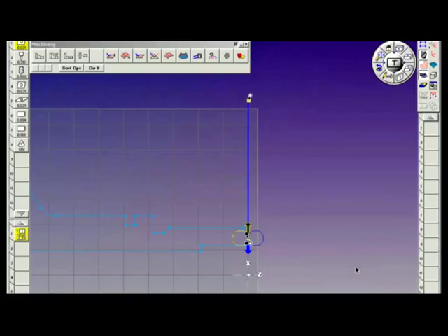I drag that off slightly above the defined stock. You notice that even if I drag it over to the side, it'll snap in line with the selected feature. The fact that the white square is on this feature locks the machining marker to that feature. So we'll just drag it slightly above that. The black circle marker is the end machining marker. We'll grab that and drop it right at XZ0.